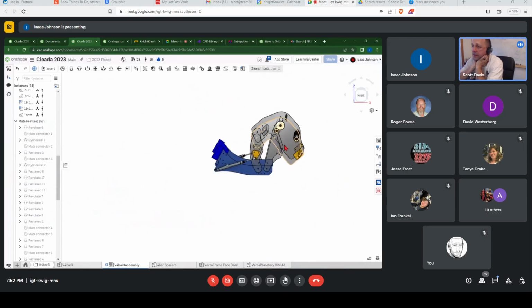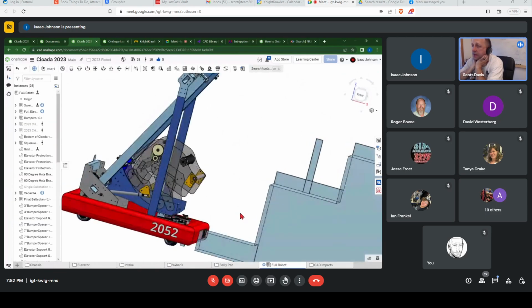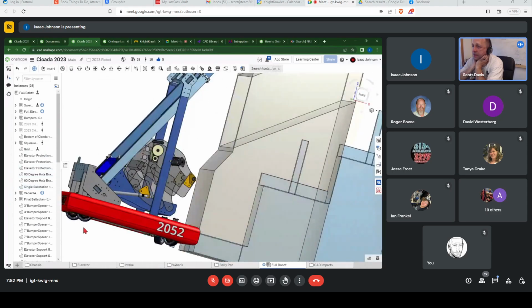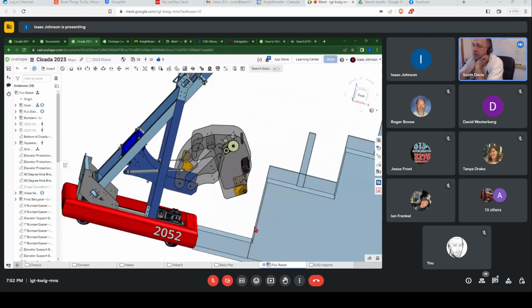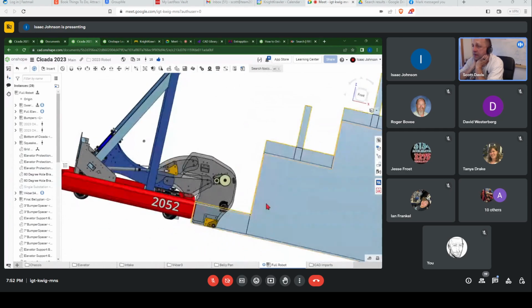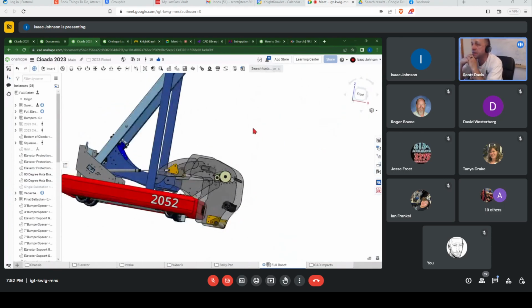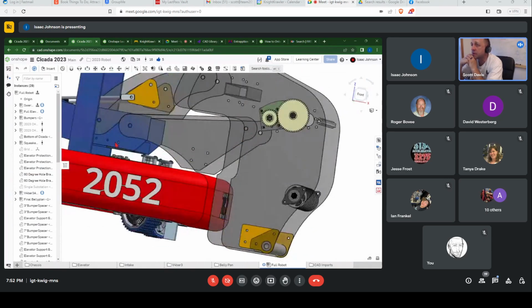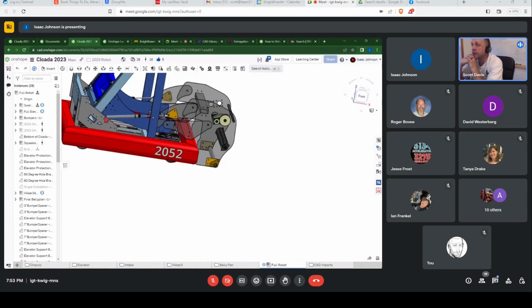If you go back to the full robot, Isaac. So yeah, right here. Let's go all the way down to the ground, and we can show how we pick up off the ground with this mechanism. So this 4-bar had to, when fully extended, and it's a piston, so it's only got 2 positions, be right on the ground to do ground pickup. You can see that one of the 4 bars is actually a brace that sits on the bumper. That creates a support so that it would sit right on the bumper when on the ground. And that's how we would do our mechanism.